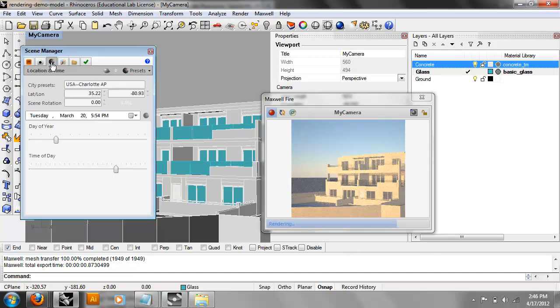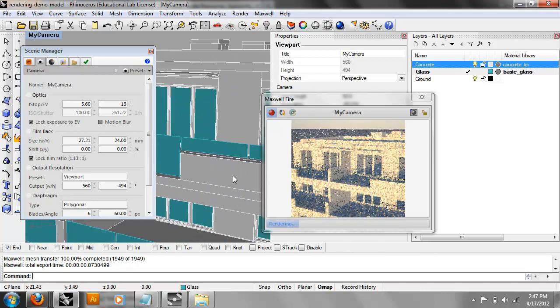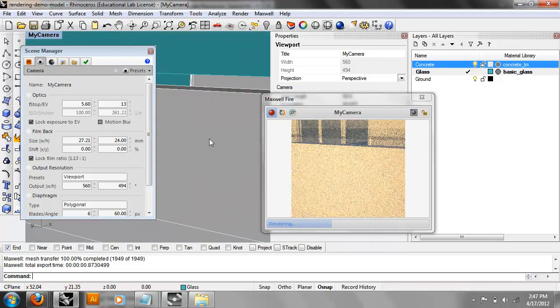Right now, what it's mostly adding for us is color, which is good, but if you really dig into it, it's not actually producing texture. Let's zoom in. Even with the fuzziness of this Maxwell preview, it's just not showing up. It doesn't look like the concrete swatch. That's because we haven't applied texture mapping to it yet. We haven't actually mapped it.